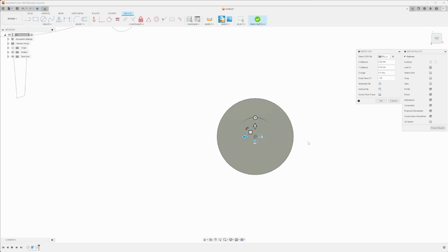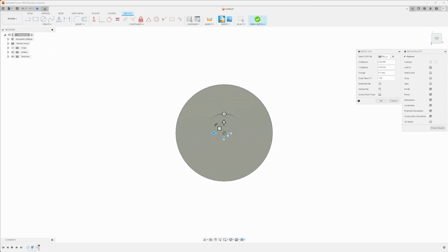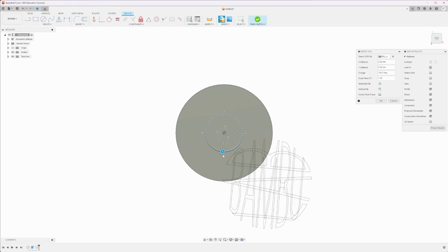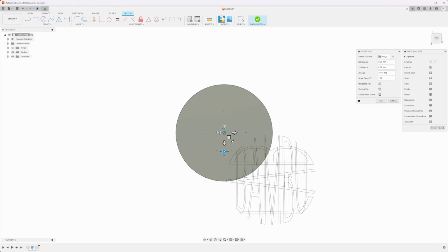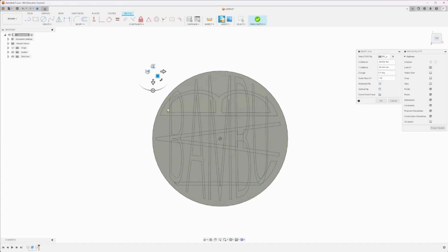That's probably because it is way oversized. So if I zoom out, you can see it's way, way, way over here. Going back in, if we have a look at our icon, if we go to this little quadrant circle, hovering our mouse on that and clicking and dragging, we can actually resize our SVG. And you'll also notice it's probably upside down. In that case, we can click on this part of our icon and rotate it around. It should snap to 180 degrees. And then we want to click on the square to move its origin point. So try and center it on our disk. And what we're doing is we're running our eyes around the perimeter of the circle and just checking that things are evenly spaced.